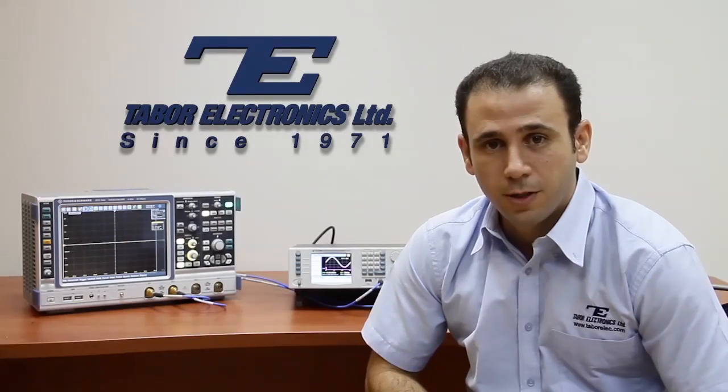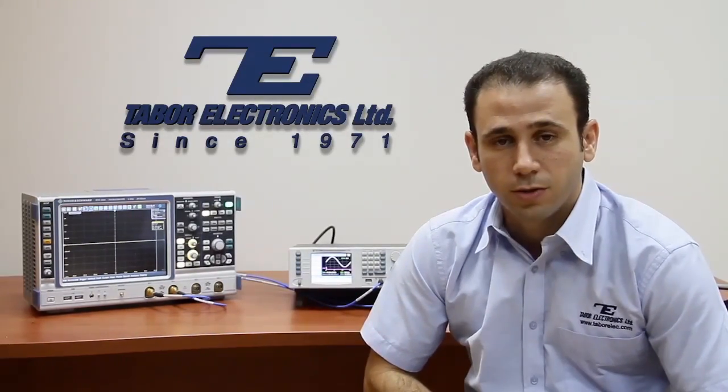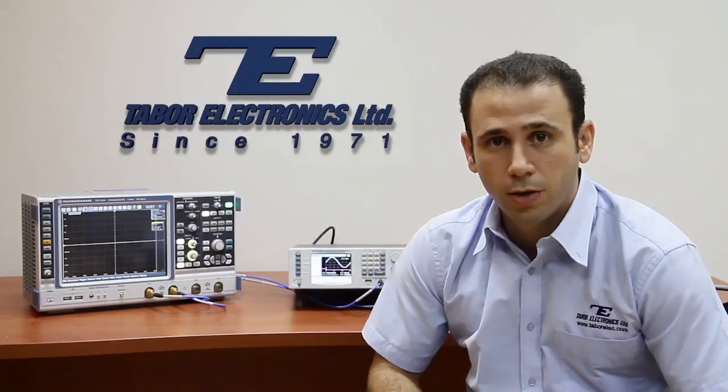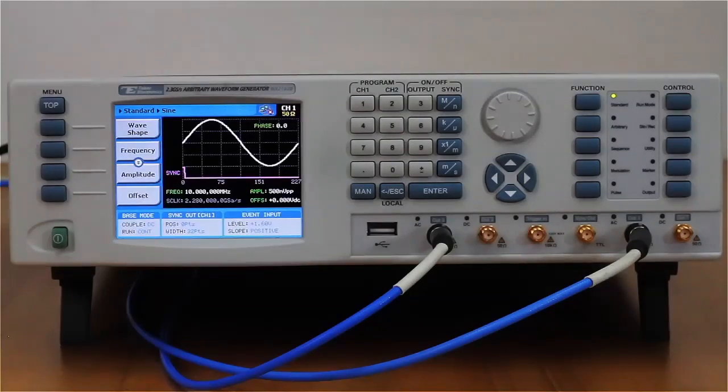Today, we'll learn about how to simply set the run mode in Tabor's WaveXciter series. The WX series of arbitrary waveform generators allows you to generate output waveforms continuously or in response to internal and external signals. To set the run mode, press the Run Mode button in the control menu.